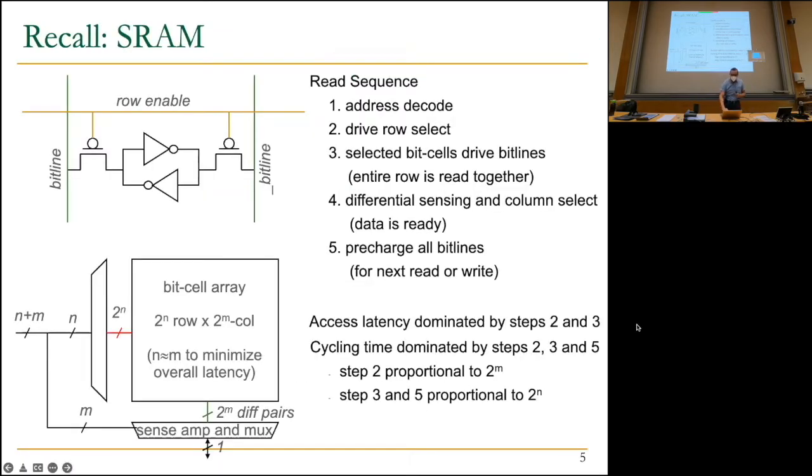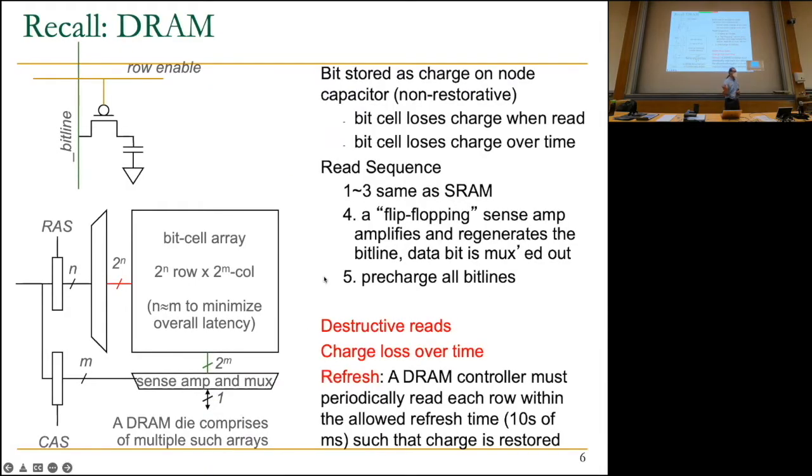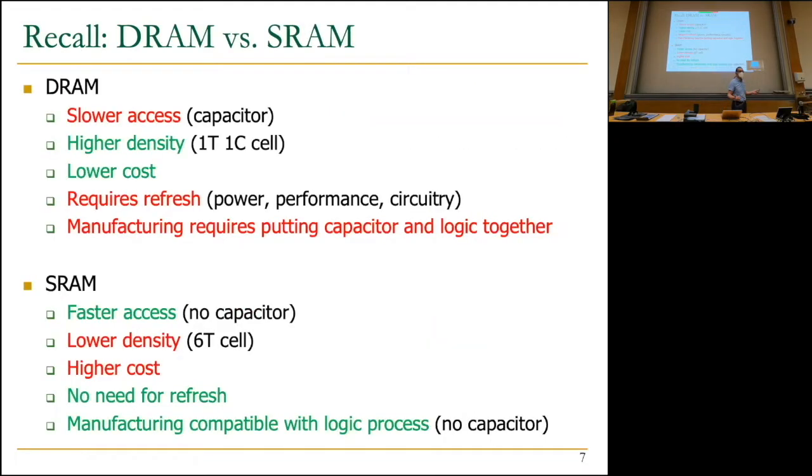And recall, we covered memory technologies. SRAM is a key technology that's used everywhere in our computing systems today. It was developed in 1960s, and it's very successful right now. DRAM, which was also developed in 1960s, is also quite successful today, right? And you know the properties of SRAM versus DRAM, which we covered yesterday, right? Because of the properties of the technology, that determines how we use the different technologies in the system. SRAM is mainly used for caches. DRAM is used for main memory.